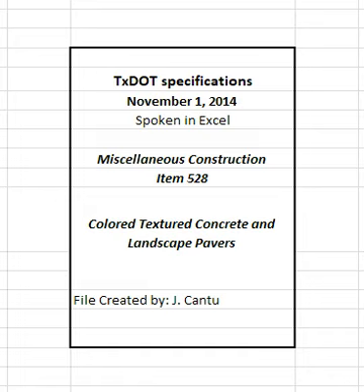Sieve size number 16 with 60 to 100% passing. Sieve size number 30 with 25 to 70% passing. Sieve size number 50 with 10 to 30% passing. Sieve size number 100 with 2 to 15% passing. Sieve size number 200 with less than 10% passing.